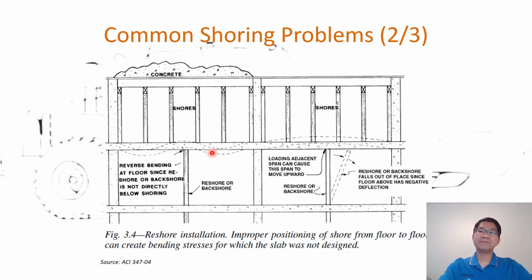So this is one of them. Deflection: normally when we design, we assume the slab deflects with maximum deflection in the middle, but in this case it goes up, which is opposite to where you put the rebar. We tend to put the rebar in the area that has tension, because concrete is not good at tension but good at compression.